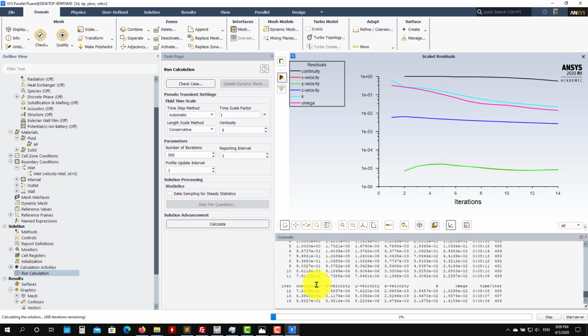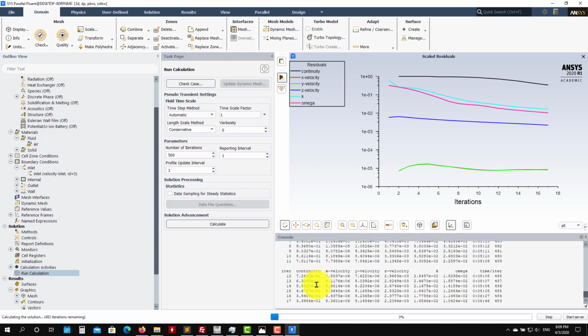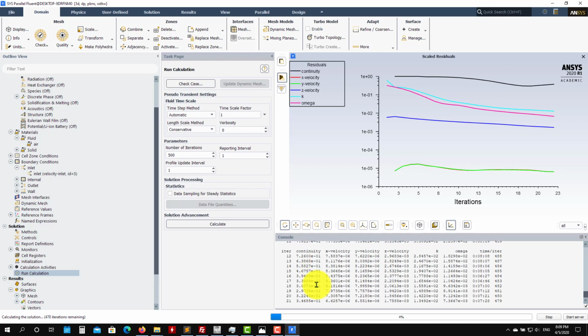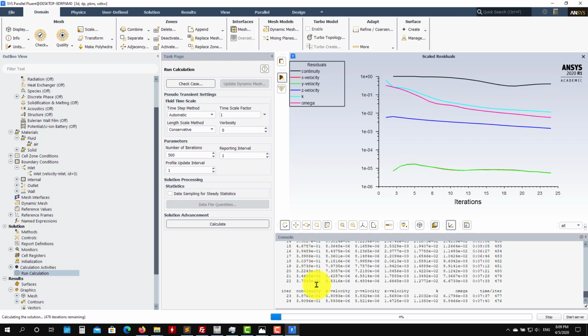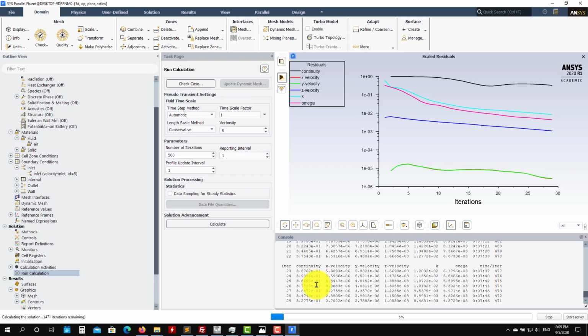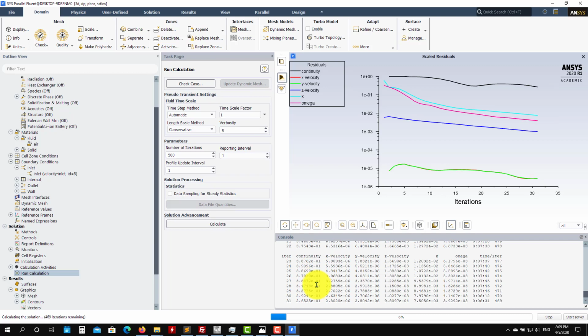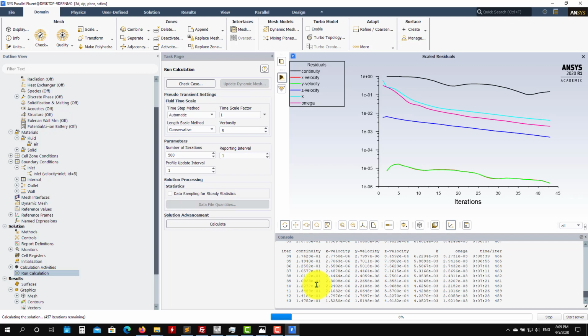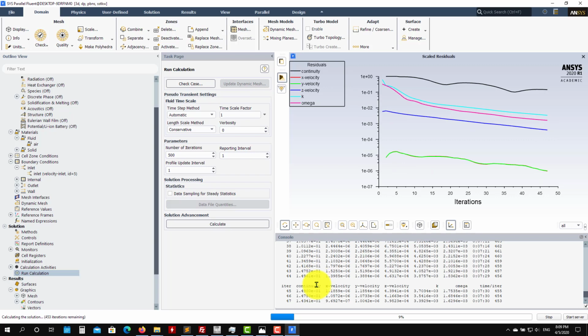But it's slower because a coupled solver means that in the same iteration, you are solving pressure and the three velocity components in one single matrix. Okay, so that's why this is slower. You put a lot of information in memory. Instead, with the segregated solver, you first solve for pressure, then velocity, component U, component V, W. So it is much faster, uses less memory, but it might take more iterations to converge. So probably in this case, the SIMPLE solver is faster.